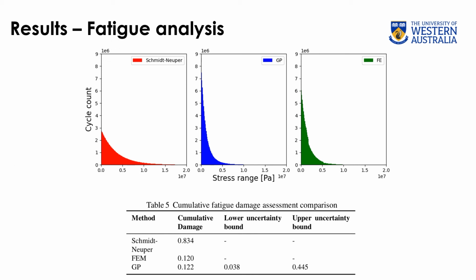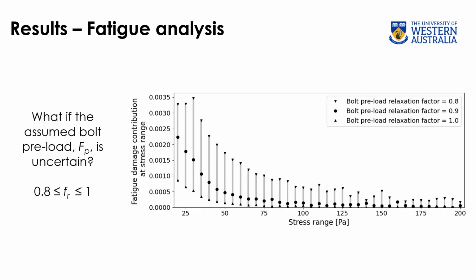These bounds are quite wide and reflect both the bounding method used and potentially the variance in GP prediction discussed previously. Through the efficient computation of the GP surrogate model, we now also have an accessible method of querying the uncertainty of the damage prediction in response to variation on the input space. This may be utilized in a full Monte Carlo simulation to assess fatigue damage uncertainty against assumed distributions of input parameters.